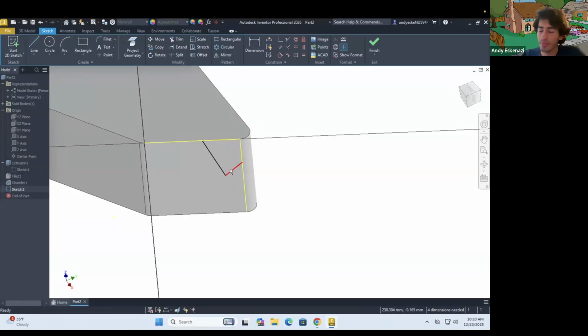These lines right here are really positioning lines because what I really want to use them for is to identify that point. That point is where we are gonna now grab the circle and draw the circle that eventually will become the hole. Now, the thing is that there is a distinction between lines like this that are solid black lines and dashed lines. Dashed lines, which I'll show you in just a moment, they refer to construction lines or reference lines.